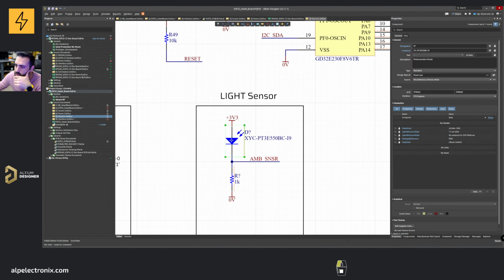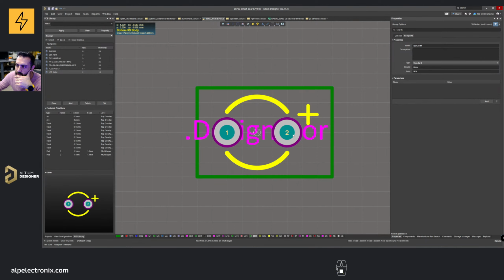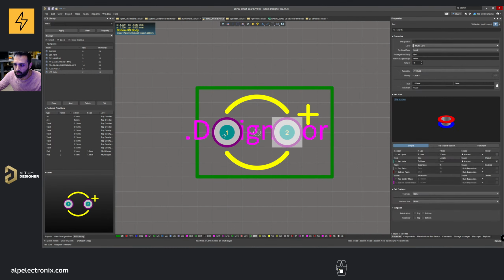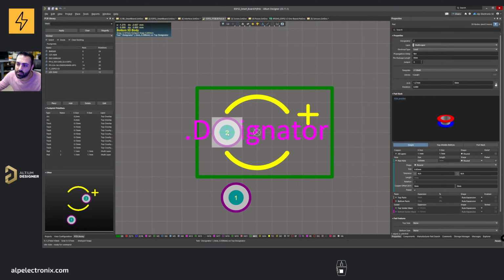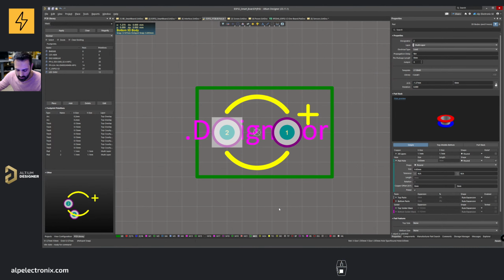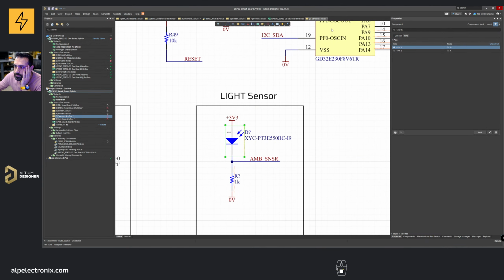What I do is I'm gonna just select this one. I'm gonna just go to properties and the pins. I will just actually make this visible. So you see anode is the first pin. So in this case, anode will come here. So we need to actually change them. Either you can change their designator, or you can just swap them like this, whichever is easier in this case.